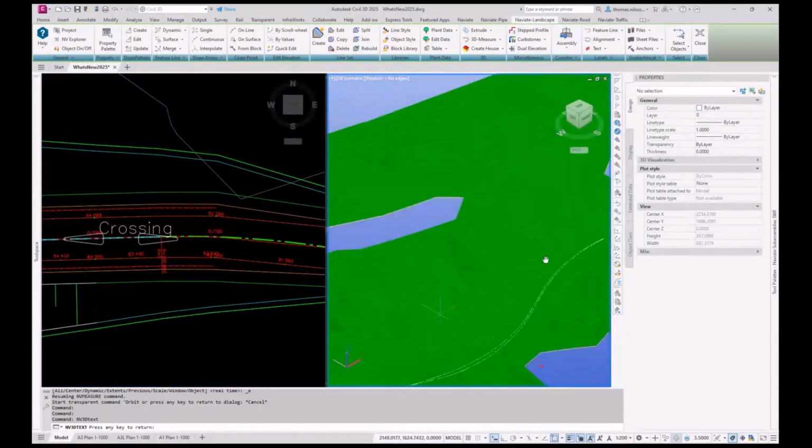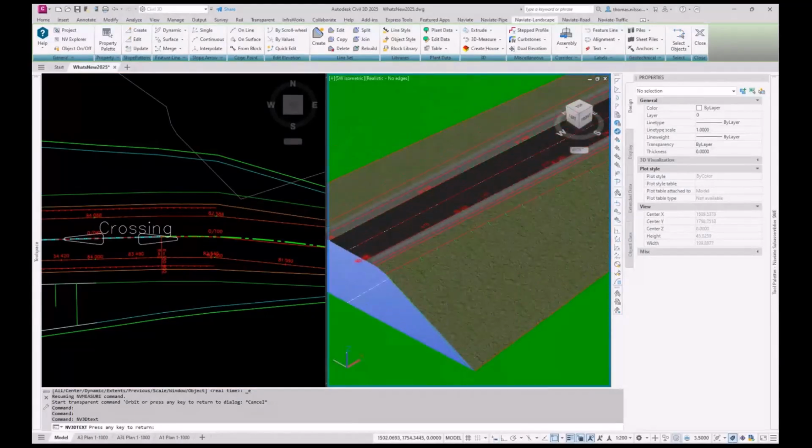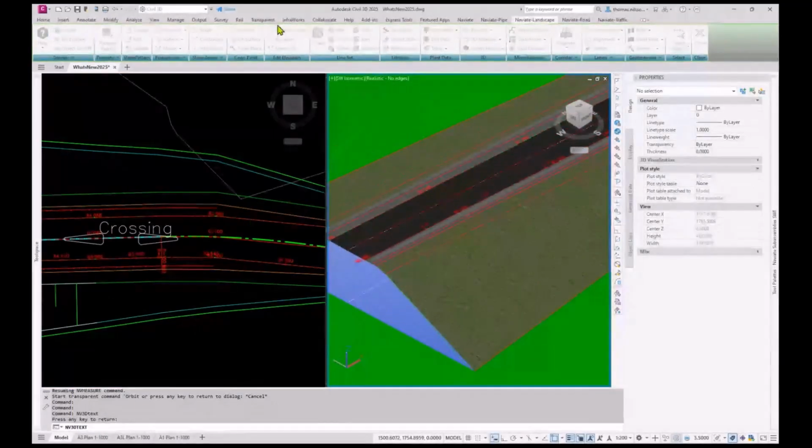Let's zoom into the road here as well. We can start off with using a text style. I want to project them to a surface, corridor top. I'm going to have no offset, dx dy. I think I have the settings set. Let's do apply. You notice that we see the text appearing there.